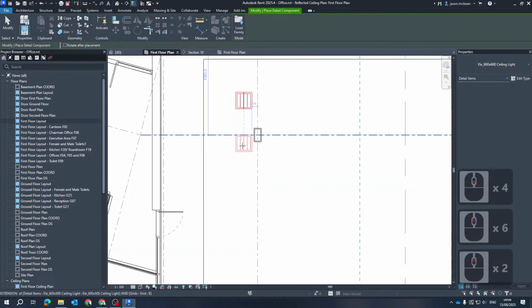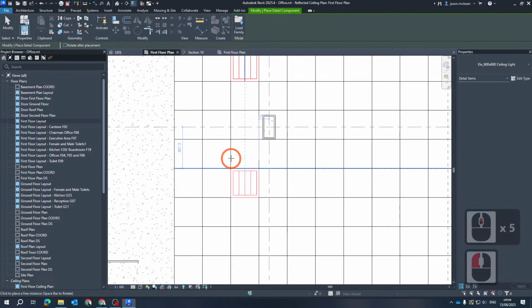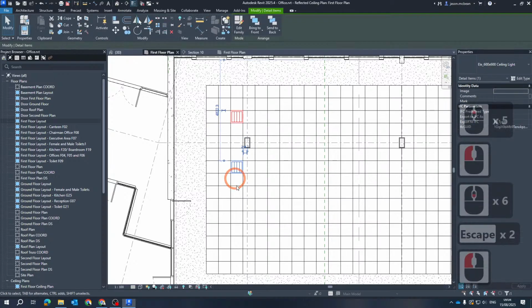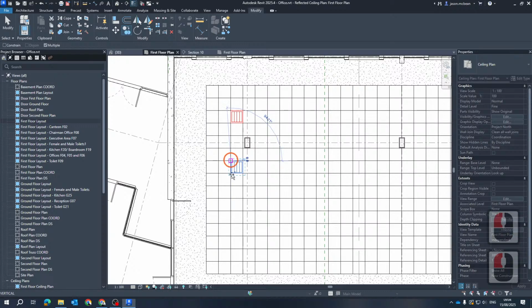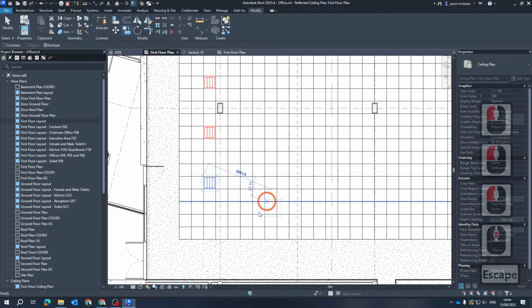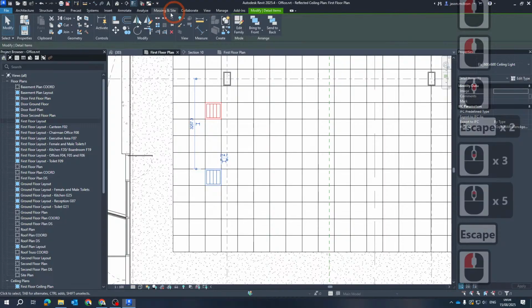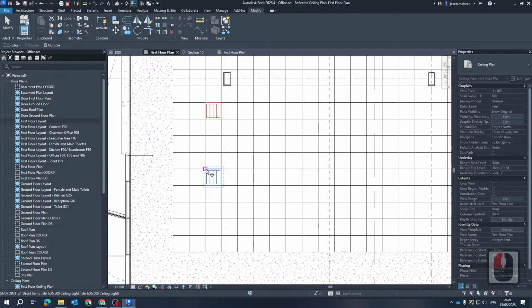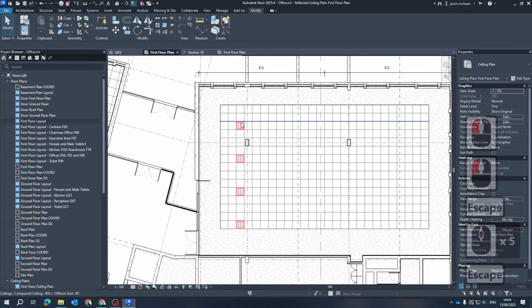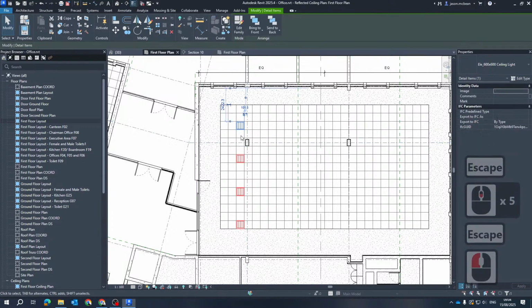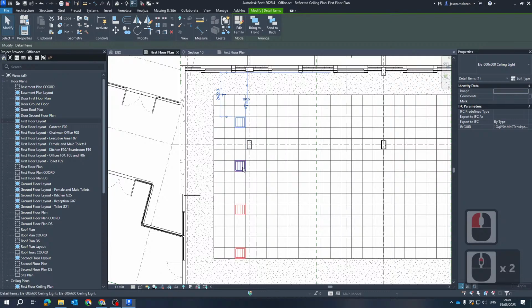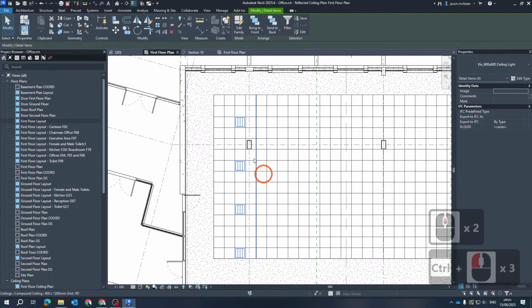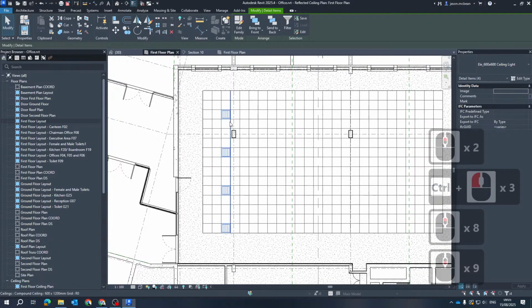Now, with this grid system, these light fittings will work within a certain grid because they get spaced at a certain spacing to achieve the required lux levels for a room. I'm just going to copy it again. So we might copy these in this direction, and I'll explain this again. Typically what they'll try to do is space these fittings with 3 tiles between each fitting, which should give you the required lux levels. So that's very important to understand.